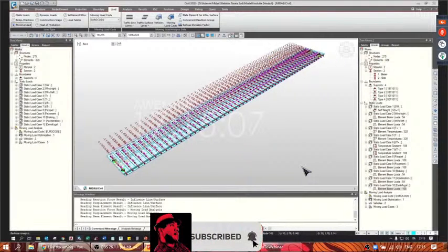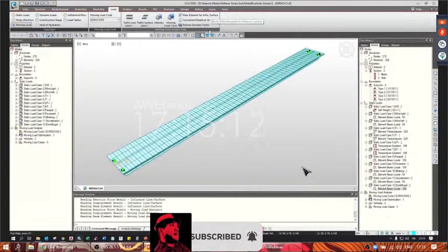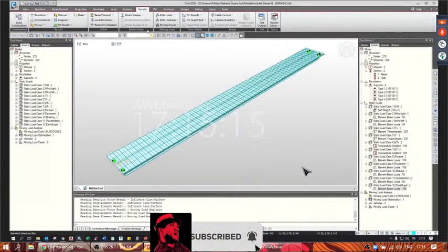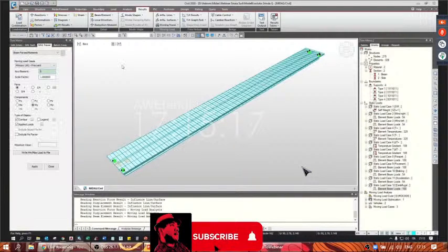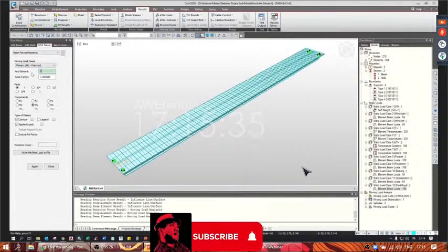Now we can check the results. The analysis has been already run. We can see, for example, moving tracer. This is interesting. Moving tracer shows the most onerous disposition of traffic load for each element. This is also a sort of test for the accuracy of the model. For example, we want to see the configuration of frequent load for maximum moment of the element 80. The element 80 is placed at the center of the span.